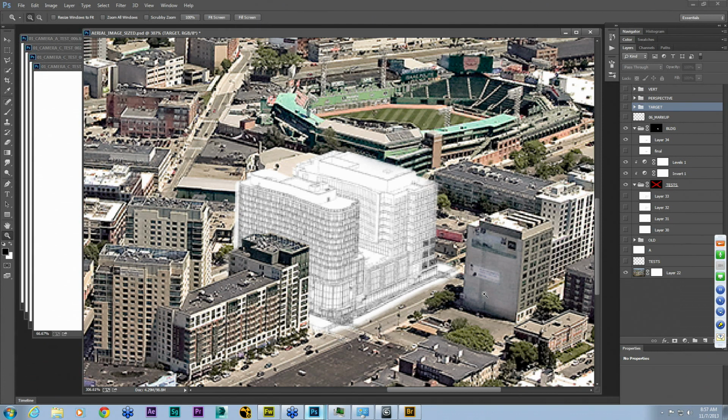If it's a 25% thing, you can use Bridge, or you can use Photoshop and some of the tools in Camera Raw to essentially use Photoshop to enlarge your image, and then use Camera Raw to start sharpening and doing some tweaks to get rid of the blurriness that's going to come from that. And you could probably do just a 25% thing with Photoshop and Camera Raw, and then match it again in Max, and work with that. But you'd still want to do your view match on your original plate and just render larger, right? Does that answer your question? That does. Thank you.